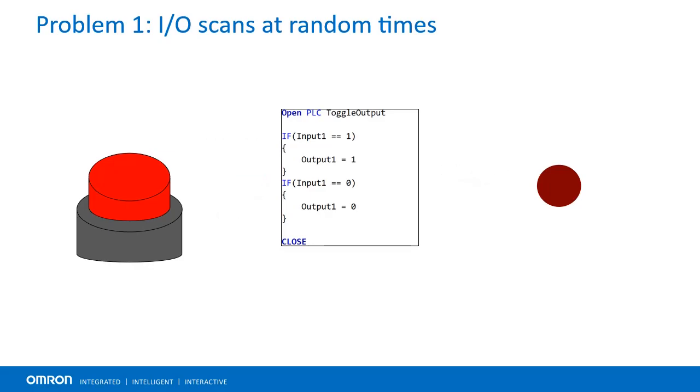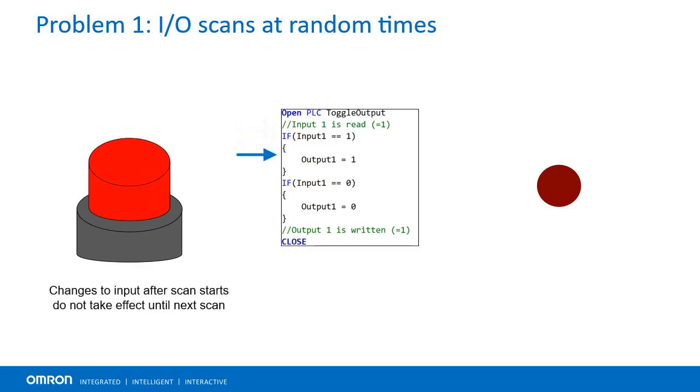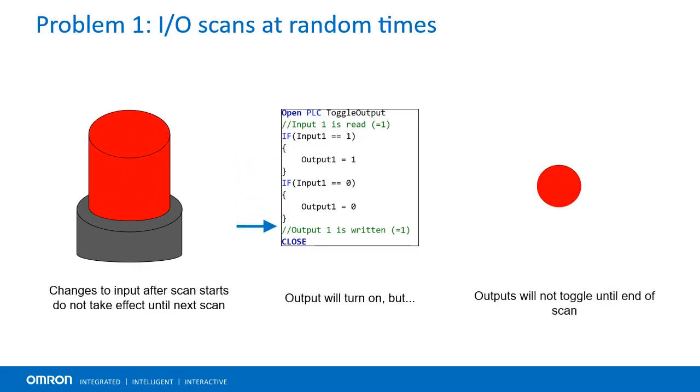For users who are more familiar with traditional PLC programming, buffered I/O will be very familiar. Using buffered I/O, inputs and outputs will be read and written at the beginning and end of a scan, respectively. This means that there's no risk of I/O changing at unexpected times and generally makes the code more stable. This also means there's no risk of a race condition in which some I/O toggles before each other. All of them are read and written at the same time.